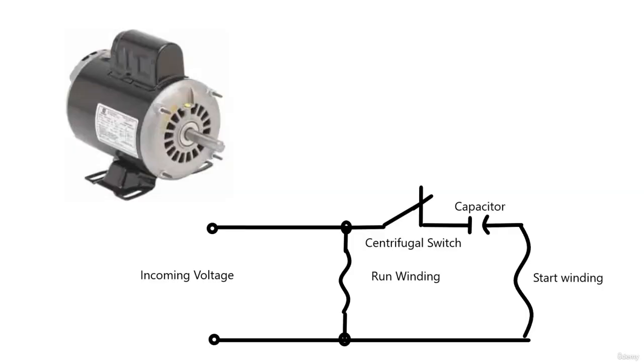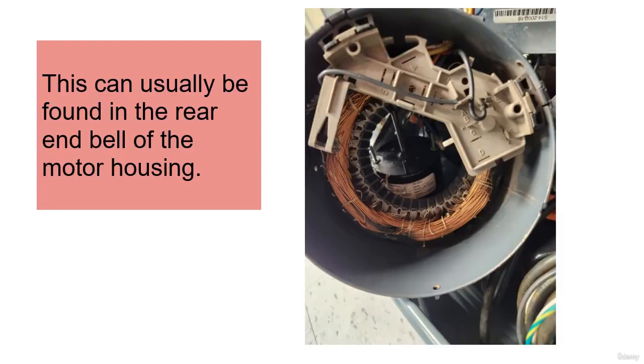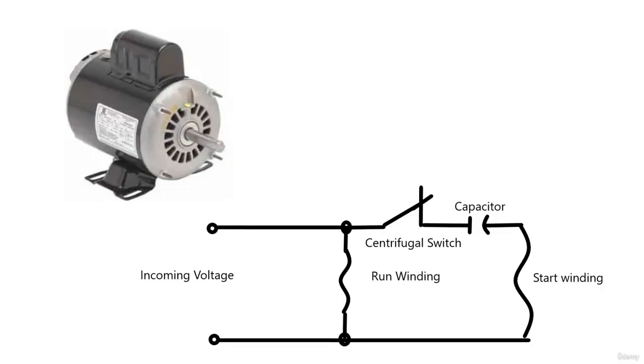In capacitor start motors, the capacitor is in the circuit boosting the incoming voltage until the motor reaches a specific speed. Once that speed is reached, a centrifugal switch inside the motor opens the start circuit. The start winding is no longer receiving power. This will be when your motor reaches its running rated amps. It usually happens so fast technicians miss it.